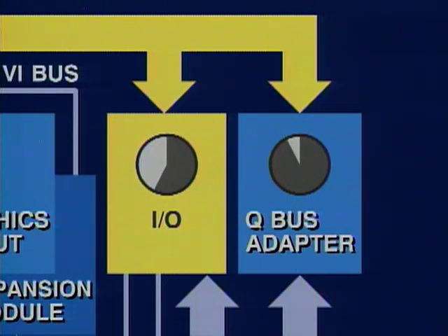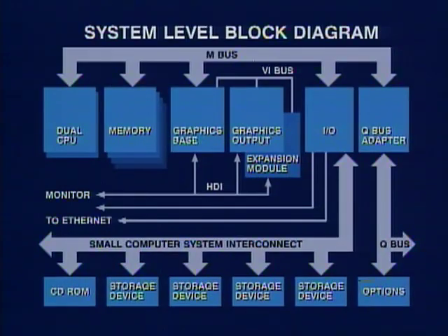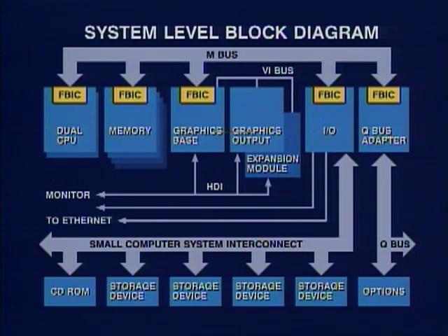More specific information on M-bus signals and transactions can be found in the VAXstation 3520-3540 system specification. Each module that interfaces with the M-bus does so through the Functional Bus Interface Chip, or FIBIC. The FIBIC is a 3-port multi-purpose bus interface and cache controller.